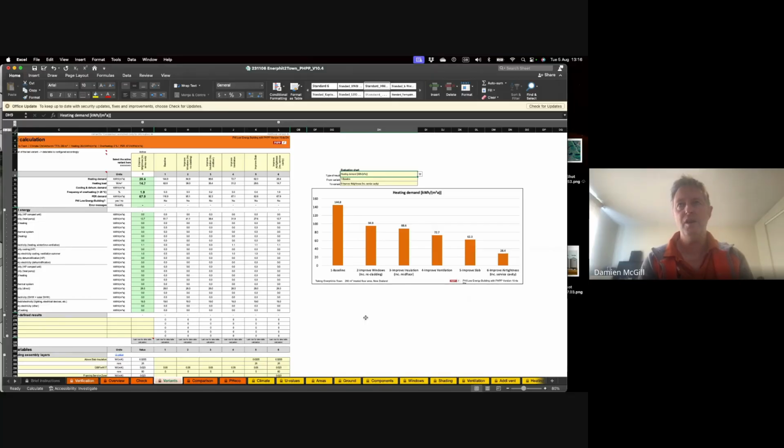And the windows that I'm using are R1, well, your walls are R2. So straight away, your windows are always going to be your weakest element. So if you can carefully think where the location of your windows are going and improve the performance of them within your budget, that's an easy way to start.